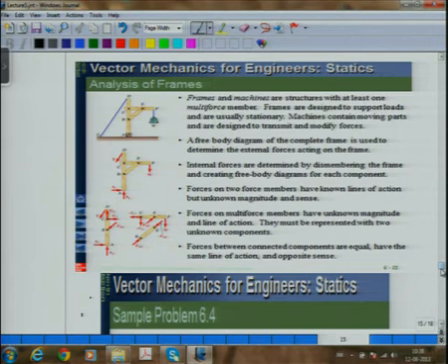When I draw the free body diagram of the straight member ABCD, at point D I will have a tension, at point C there is a pin, so I will have Cx and Cy. At point B I will have just a single force BE, acting along the line of action of BE, because BE is a 2-force member, and then at A I will have Ax and Ay.